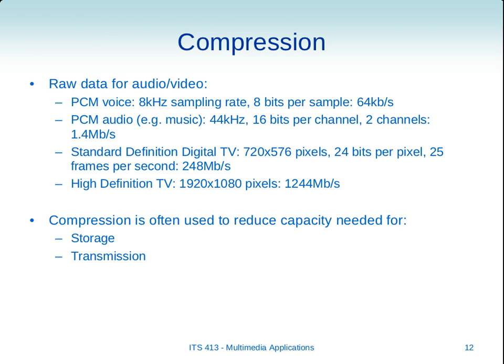And in music we often will have stereo, 2 channels, left and right channel, and a typical sample size is 16 bits per channel. So the size of recording music at this quality, 44,000 times 16 bits, multiplied by 2 because we do that twice, one for the left channel, one for the right channel, for stereo, consumes 1.4 megabits per second.